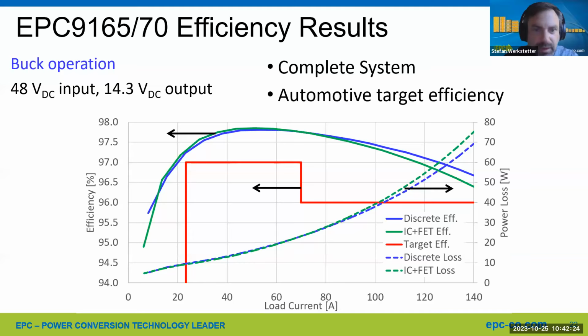And probably the last question, what is the maximum switching frequency limitation for EPC new products? It depends on the losses and on the thermal management. Our devices can switch really fast, especially the small ones. We have applications where they are switched at 50 megahertz, power conversion applications, in envelope tracking converters for 5G radio stations.